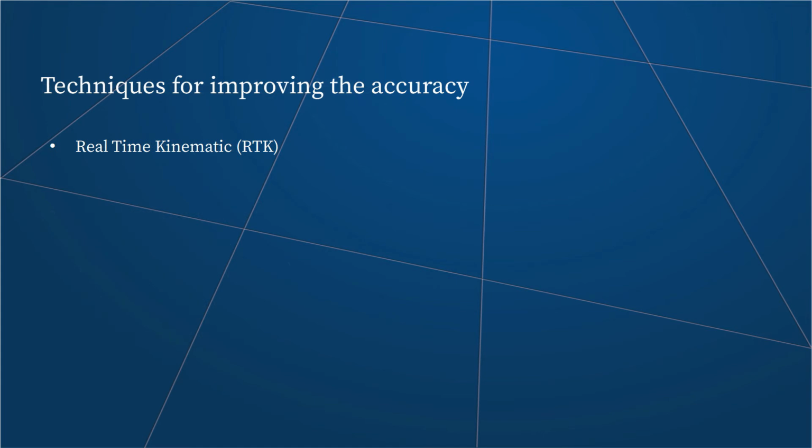Okay, let's see what could be done to reduce all these errors. The first method for reducing the errors and increasing the accuracy is real-time kinematic, or RTK. RTK was developed back in the days when selective availability was active, and it is a very simple method requiring two identical GPS receivers. One receiver is called the base station and it's not moving.